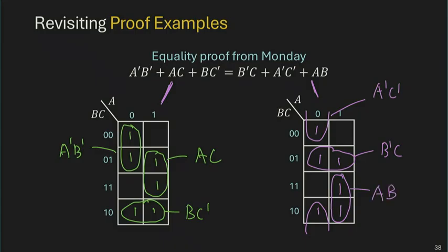Now if you ignore the colors, they really cover the same ones, the very same min terms, in different ways. You're almost rotating it a little bit by one position, and you get entirely different representations. But fundamentally, they cover the same ones, and both of them are equally minimal. These three product terms are the minimal way to cover all of your min terms.